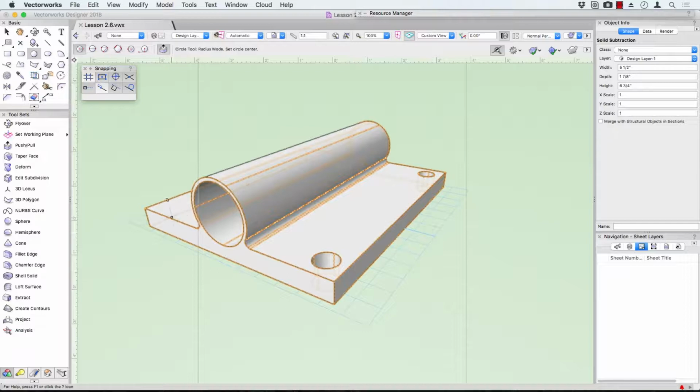We've got this one over here to do now. So find that edge, hit the T key, find this edge, hit the T key. Now you might notice I don't go near the midpoint to find when I hit the T key. It always seems to cause me a little bit of trouble. So 0.25, enter once, enter again, and let's click, come through, Option or Alt, click again.